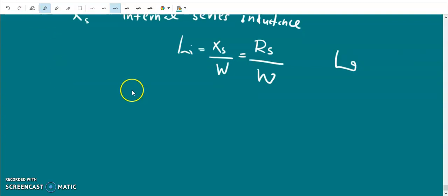And we have also seen that for the calculation of power loss in the conducting plate having finite conductivity sigma c, we need an axial electric field Ez so that the Poynting vector exists in the y direction. So the electric field is there in the direction of propagation.